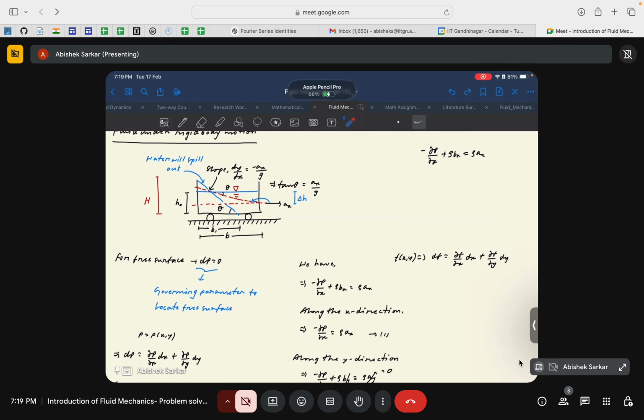If you remember, in the last class also, we discussed the governing equation for fluid statics. So this was basically the governing equation for fluid statics. Now the basic question was, if the fluid is static, why is there an acceleration term? I told you this acceleration term exists because there might be scenarios where the fluid is in motion, but still the net shear forces would be zero, and if the shear forces are zero, then these scenarios also fall under the umbrella of fluid statics.